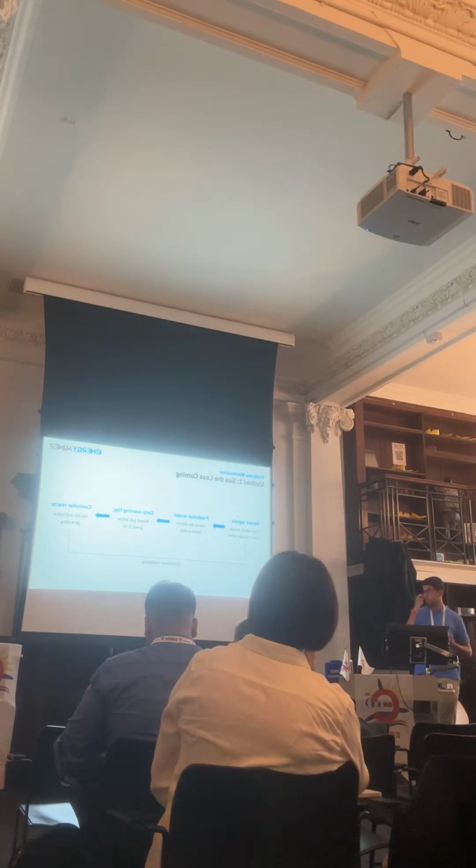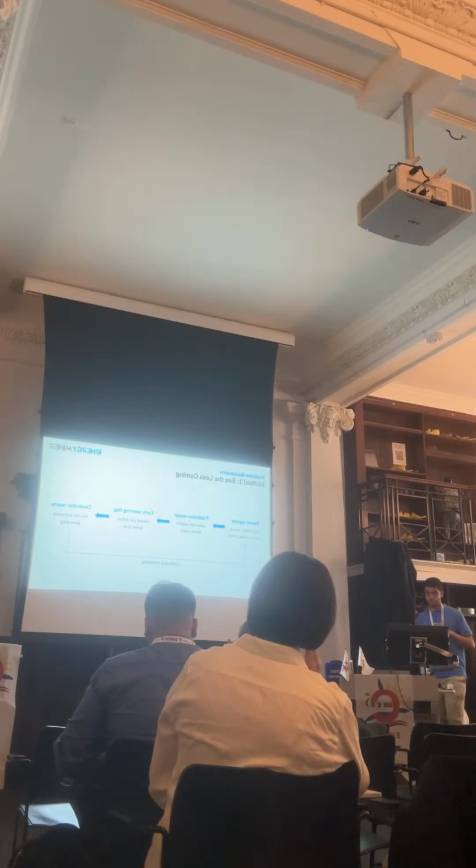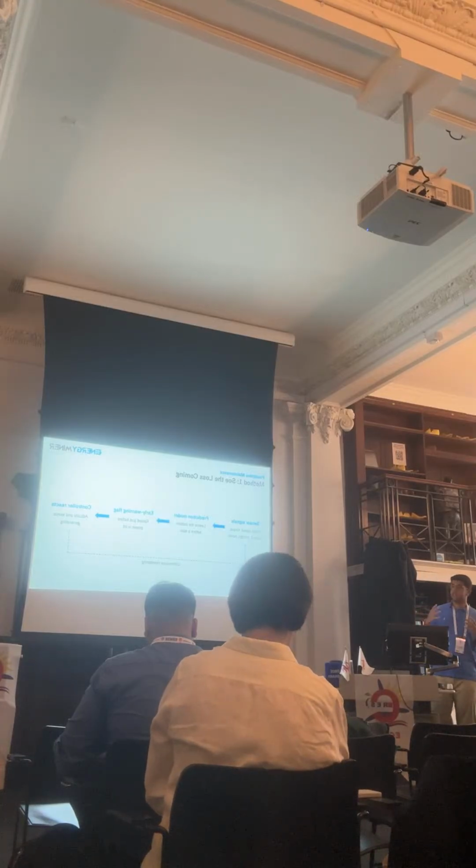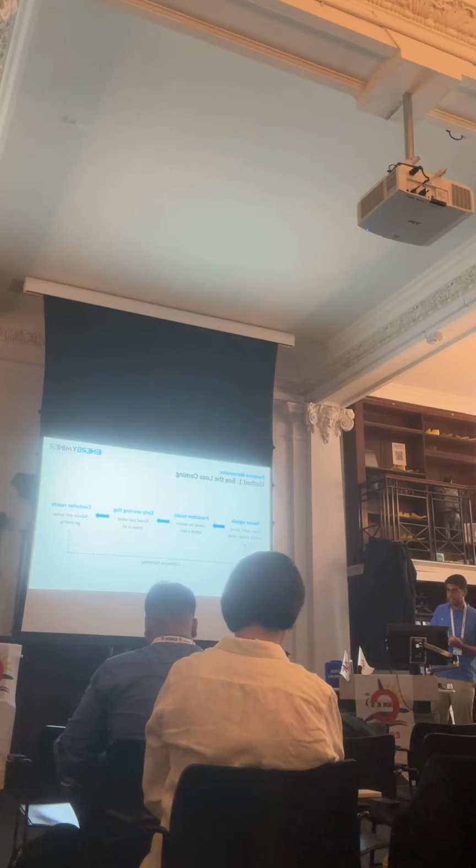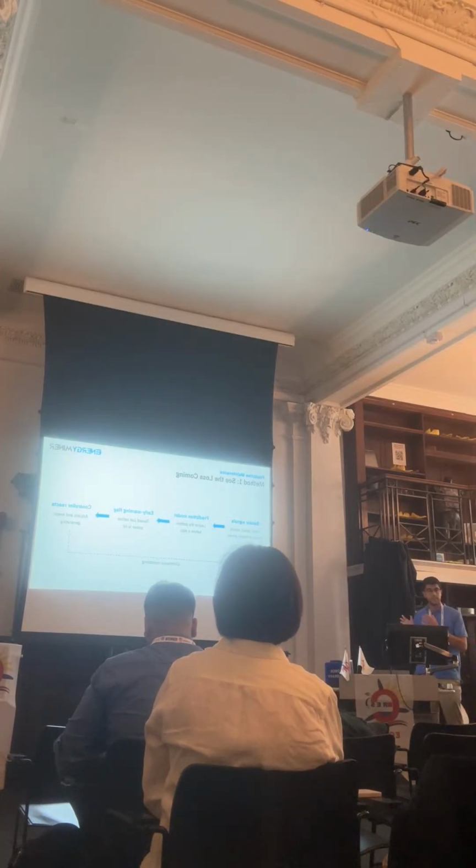That's why first we need to have the fault detection, to be able to understand what's going on in the system. So first we need to create the scenarios for the failures, and then we're able to understand if there's a failure or not. Because if we are not sure about the failure's characteristics, we cannot identify them as a failure.